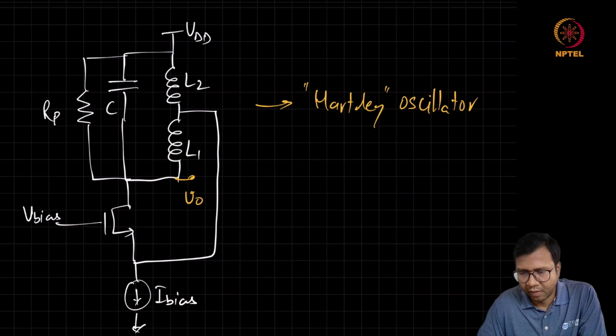Then we have a op-amp based phase shift oscillator. We will see that for wireless application, we need very clean local oscillator signal. At the same time, the oscillation frequency is also going to be in gigahertz. So most of the time, we'll find that this kind of LC based oscillator only meet the spec for high frequency as well as spectral purity.